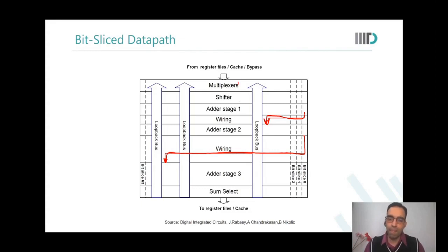And sir, what is this loopback bus? This is information going back saying that there is an overflow or so, a system level bus, which would give information to close any loops that were there. Now addition is completed, so you can accept the next input. It could be ready signals, it could be those things.